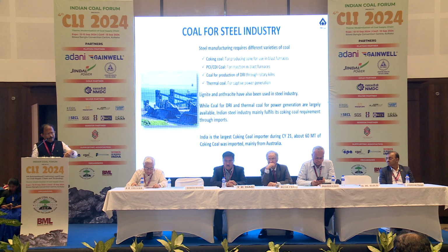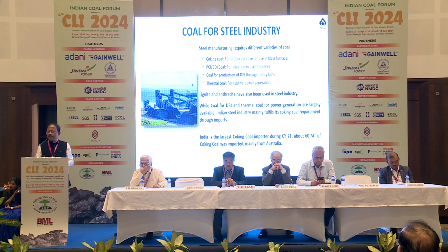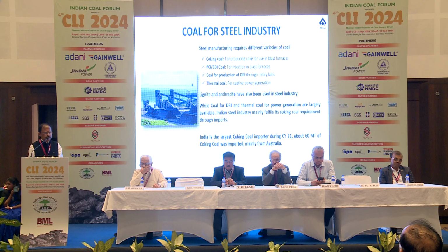So coal has multiple uses in the steel industry. Coking coal is used for charging in the blast furnace in the form of coke. PCI and CDI, pulverized coal injection: we inject some coal directly into the blast furnaces. That gives some operational and cost economy.